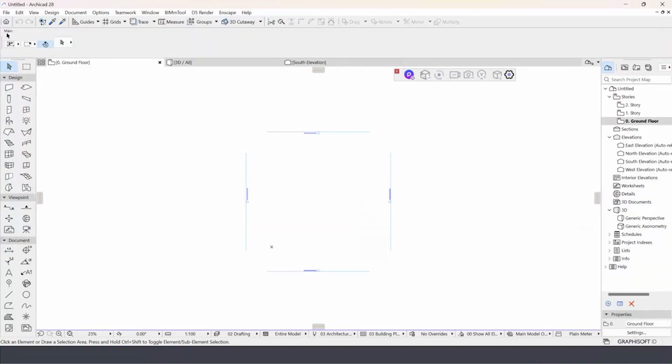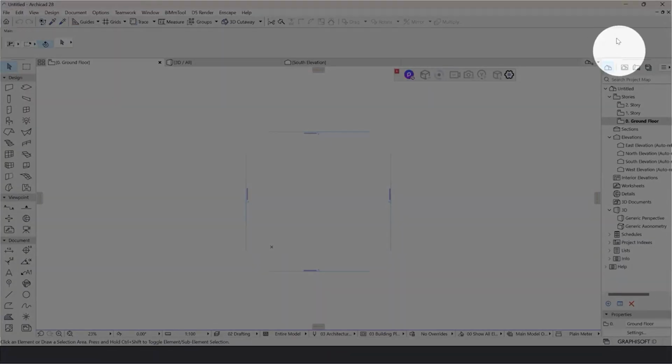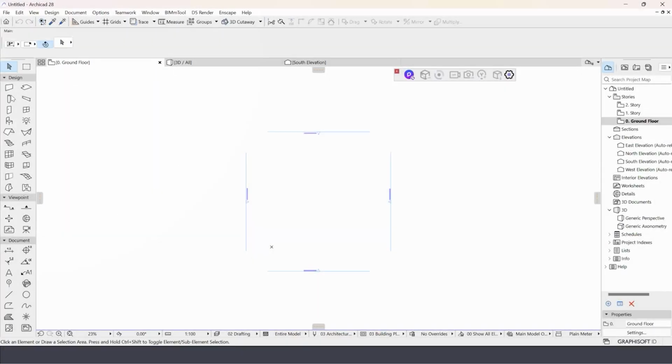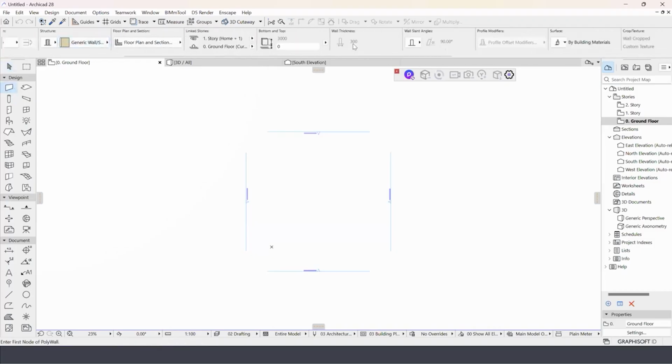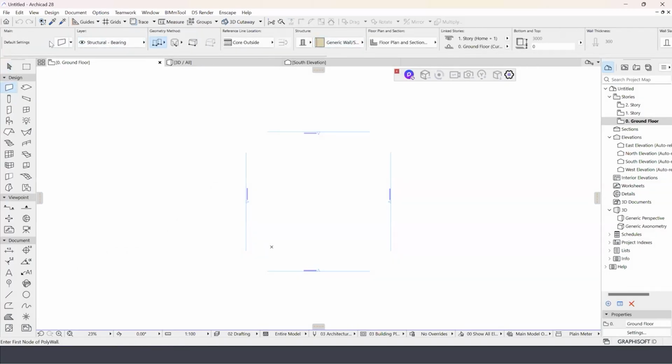And below that, we have something called the info box or info panel. This particular area is an interactive area where, if I select something, this interface part will automatically adapt. You can consider it like element properties. So whatever properties there are of the elements that you place in ARCHICAD, their properties will be visible. It can be before drafting or even after drafting; both ways we can make use of it. Anyway, we will get into it and you will understand how it is being used.